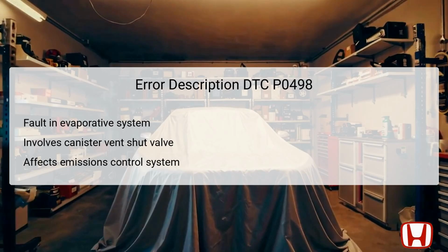If the circuit shows low voltage, it could indicate a wiring issue, a malfunctioning valve, or problems with the engine control module, ECM, that controls the valve operation. A thorough understanding of this component's role and position in the vehicle will guide technicians in accurate troubleshooting and repair.